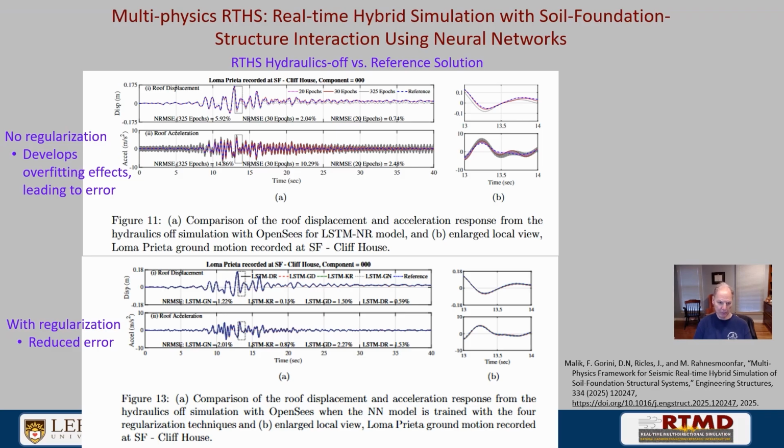So you can see when you compare the two, if the neural network is precise, you should get the same answer, and we're not. Displacements, the upper part here of this figure, maybe don't look too bad. This is a close-up. But notice something here. As the epochs, that is, as you increase the number of iterations, the RMS error gets worse. This is kind of disturbing. You would think that would get better. And for instantaneous accelerations, which typically you are interested in because of non-structural components or even some structural components, there's a lot of noise here. This is almost worthless.